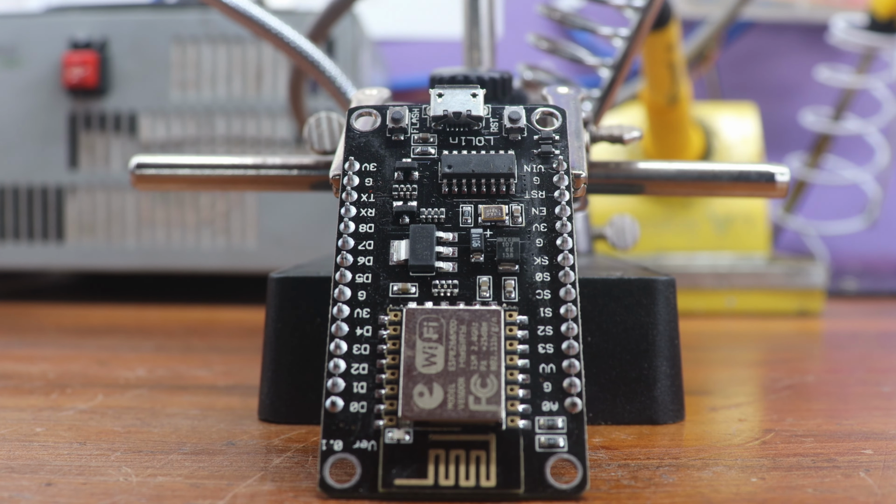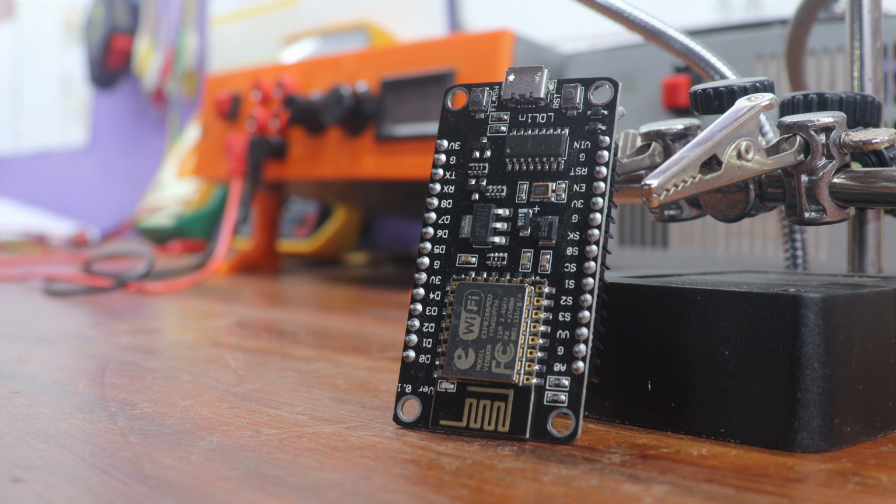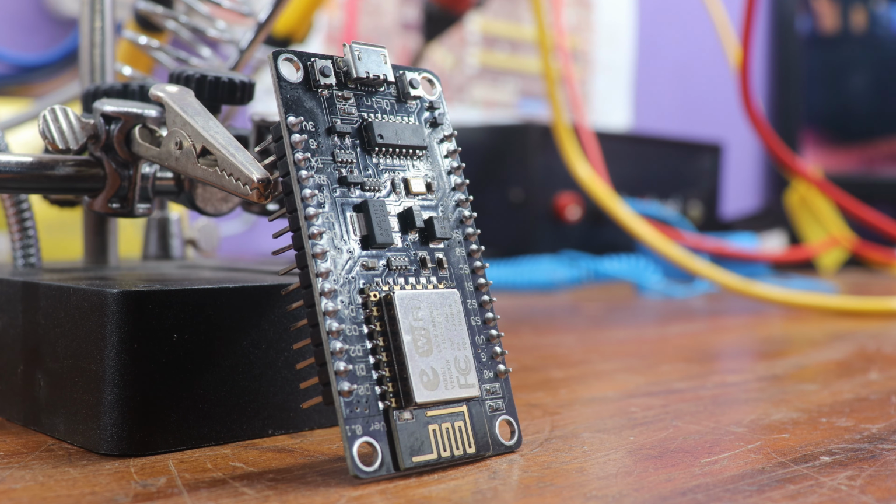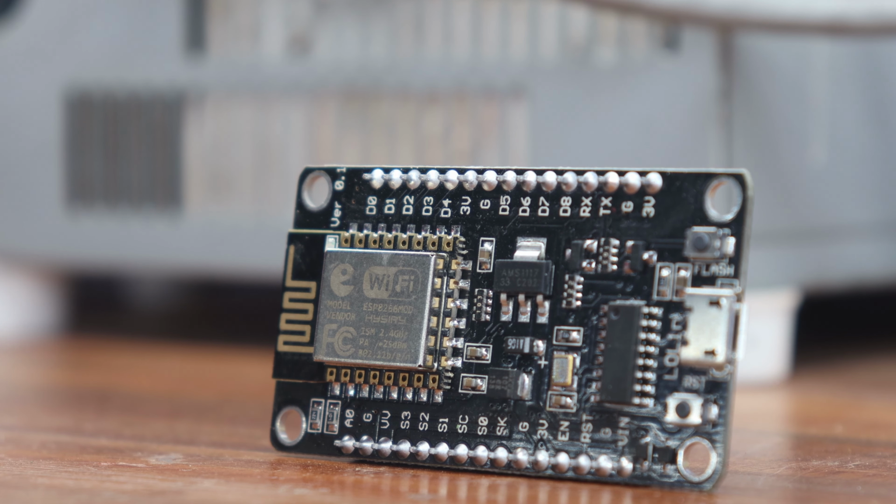The NodeMCU is a crucial component in this project as it serves as the brain of the system. It is a low-cost Wi-Fi microcontroller development board based on the ESP8266, offering a platform for IoT applications. The NodeMCU has built-in support for Wi-Fi connectivity, making it ideal for use in wireless projects like this doorbell system. It controls the DF Player and triggers it to play the pre-recorded audio messages, as well as the traditional doorbell.